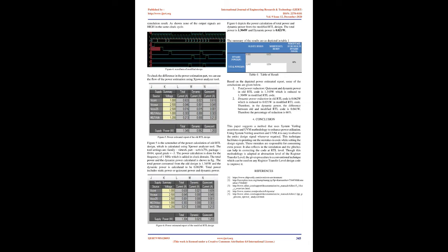We found glitches in the FSM design as depicted in figure 3 because, as per the specification in the TCP/IP protocol, for one clock cycle only one packet should go high. But in this case, a few packets or outputs are going high at a time, in the same clock cycle. After getting simulation results, the unwanted signal which is affecting the power consumption will be corrected. Figure 4 is the new bug-free modified design.